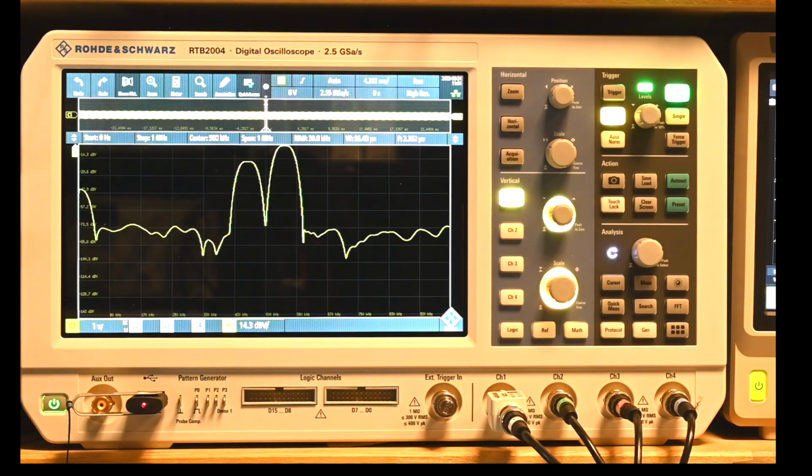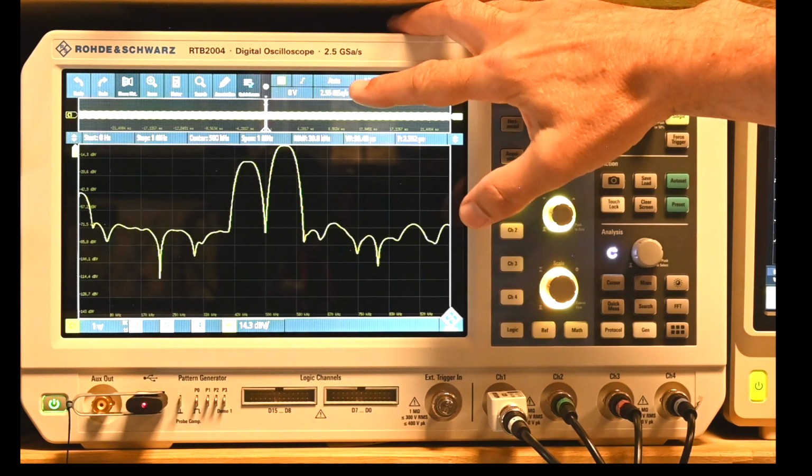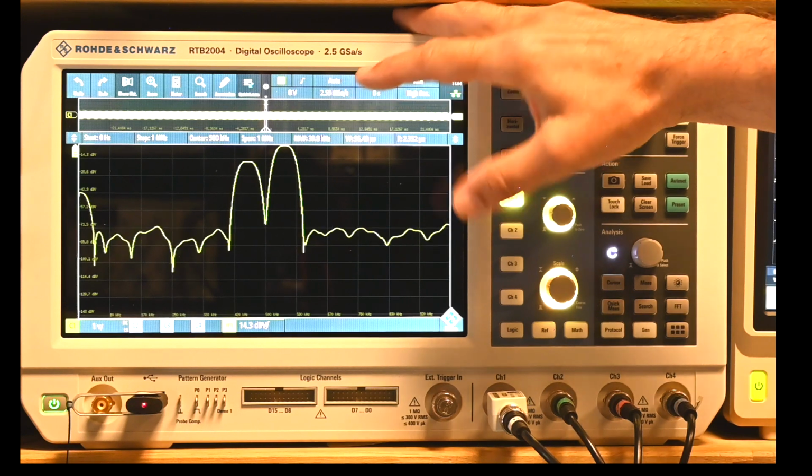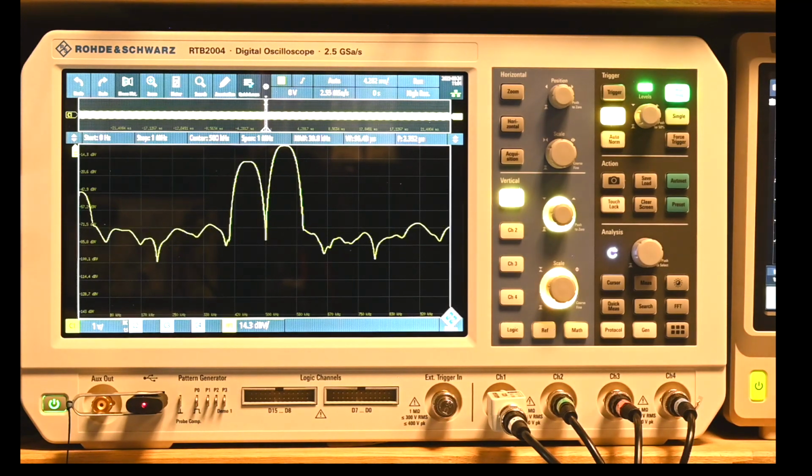So now we know that whichever setting we take, and I tested this also for a number of other frequencies and settings, the sampling frequency and thus also the Nyquist frequency that we see here on the screen is exactly what's being used for the FFT analysis. And this is good news. At least that makes the whole process a bit more predictable. Now we know, given a certain input signal that we want to analyze, whether the scope is able to properly show it, or whether we should be worried about seeing alias-type effects instead of real things.